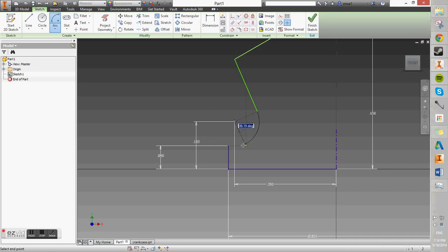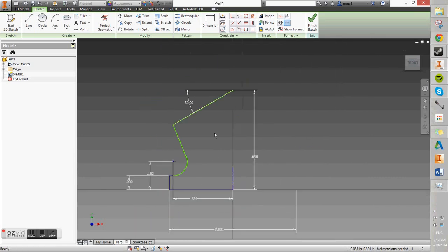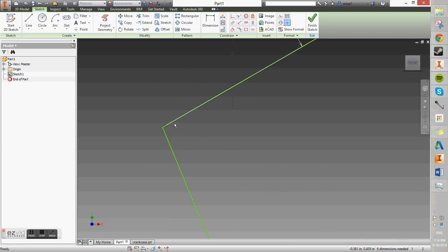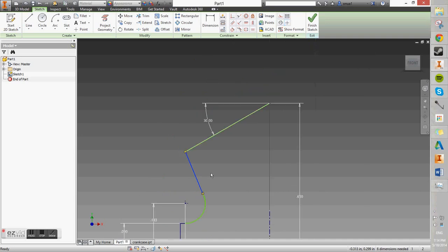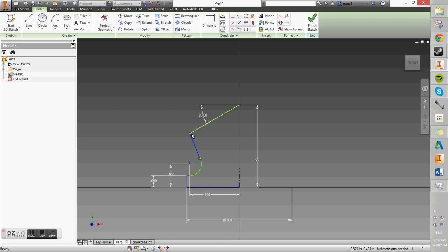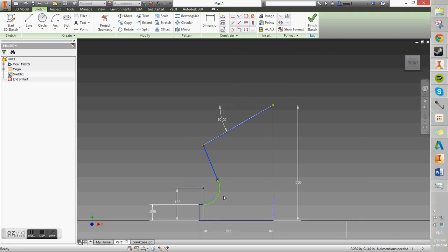And starting from the endpoint there, and it'll show a little imaginary line telling us that it is tangent. So let's just stretch that across, and there we go. That should finish the curve. Now if you notice, we only have half of our desired shape. So what we're going to do is select all of our shapes, all of our lines. All you have to do is click and then hold shift, and when you hold shift it'll multi-select. Whoops, that was caps. So let's hold shift to multi-select, scrolling in and out using the wheel to find those hard to reach places.